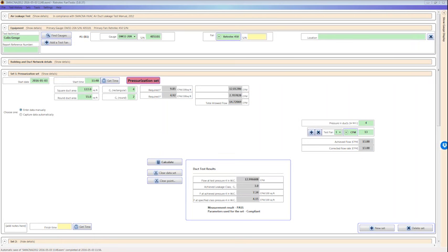What you will notice when you're testing ducts, when you have the AT feature on, let's say your test pressure is 4 inches, which is pretty typical, then you start at the fan, you get up to 0.1, 0.2 inches. You'll notice when the AT feature is turned on that the result doesn't change a heck of a lot when you go from 0.2 all the way up to 4 inches. So when you use the equipment, watch that and you'll be surprised at how little the answer actually changes as you go up to the test pressure.